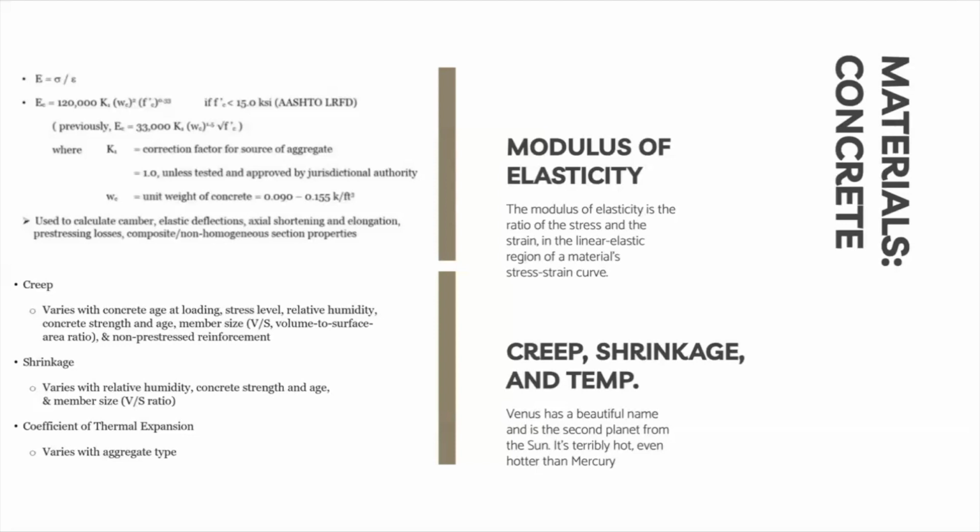Additionally, over time, concrete experiences creep and shrinkage, particularly relevant in pre-stressed concrete members, leading to significant losses in pre-stressing force. The extent of creep and shrinkage depends on factors like concrete aging at loading, stress level, relative humidity, strength, member size, and presence of non-pre-stress reinforcement.